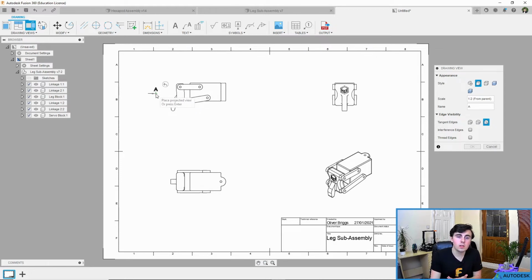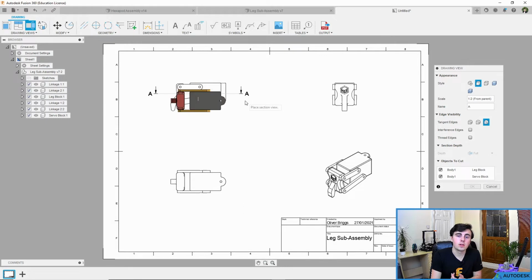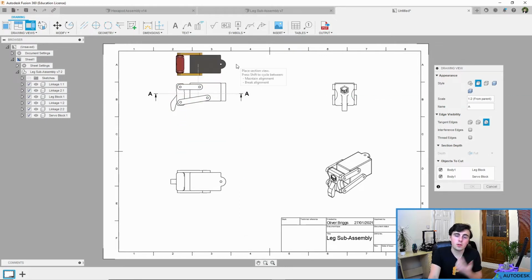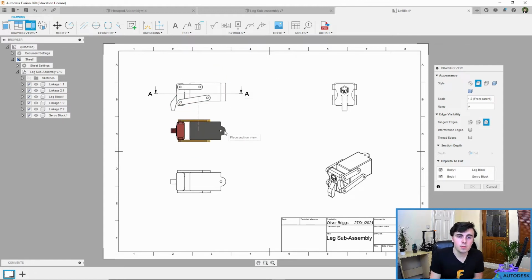You'll click on one side of your section, you'll click on the other side of your section, and then it'll ask you for a direction once you click on the tick. If you put your section above, then this is what changes the arrows. I'm going to put mine just below, and you can click confirm, and again you can change your views and everything.